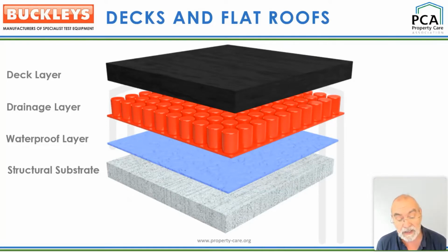And the substrate or the layer below the waterproof membrane or coating needs to be conductive and grounded. In remedial work, where there is evidence of water infiltration, it's very likely the water itself will form the ground path between the leak and the building structure. This will be very helpful in finding breaches in the waterproofing layer.